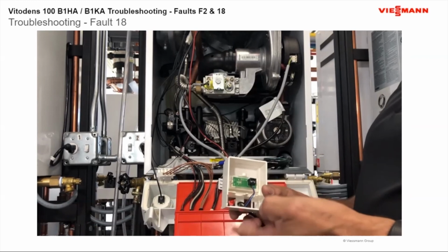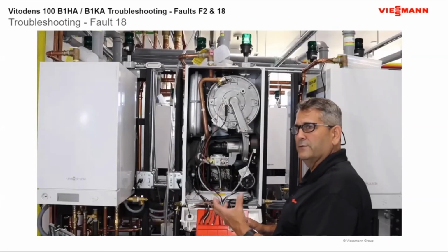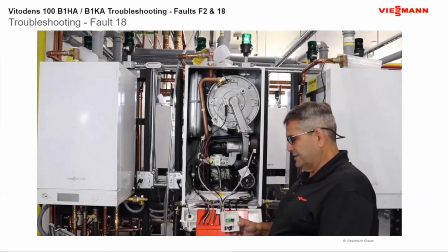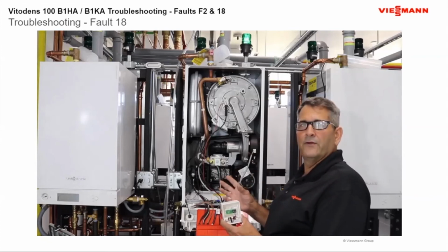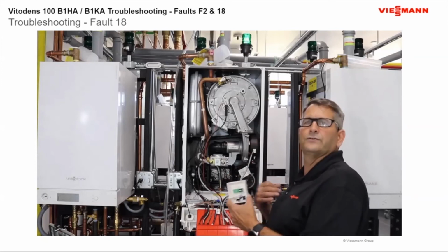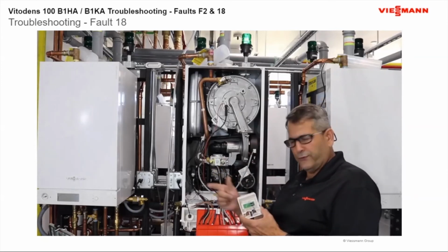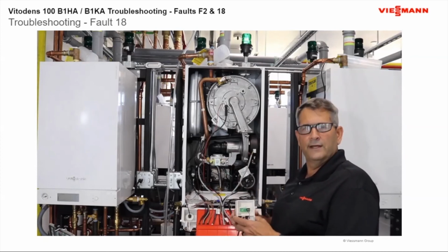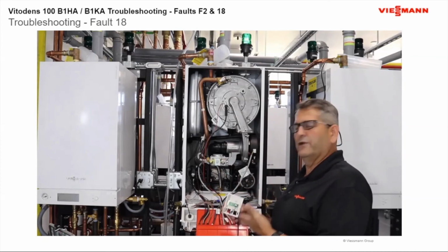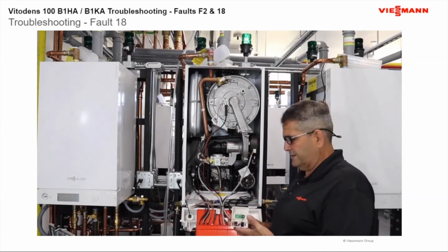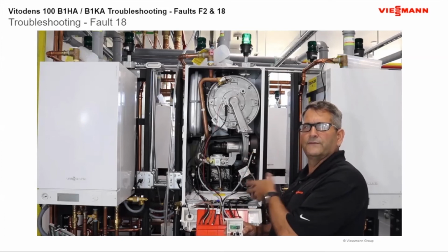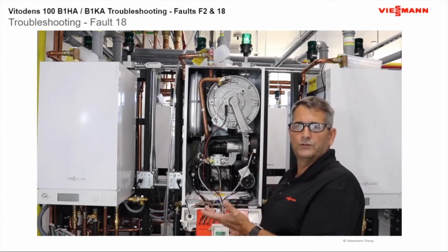But remember, sometimes we see false readings because we're either in the sun or we put it in the wrong location. And I've seen many guys put it out by their venting itself, because we already built the hole for the venting so we can get our little thermostat wire through, and then hang it conveniently near a dryer vent or something like that, which is going to fool your outdoor sensor into reading incorrectly. So you might get wrong temperatures with your boiler itself, and not enough heat or too much heat.